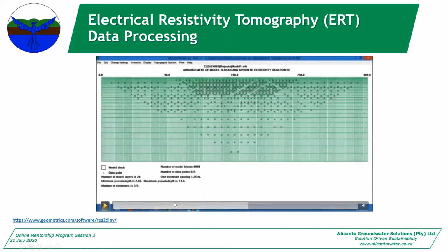And you see here's all your data points. You see how it makes this triangle. Because you've only had 2 points where you've had A and B somewhere there to read down to this one. And then B and A over here somewhere to read down to that one. So you see that's why it's better to do a longer line, because this is only a 400 meter line. So you've got a very limited data depth over here. Yeah, here is okay, but over here it's just going to be contoured. So it's not really going to be that meaningful.